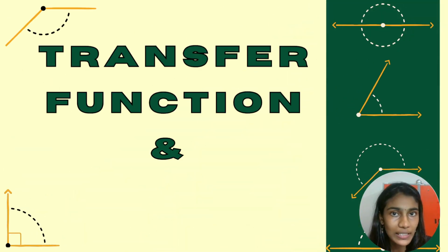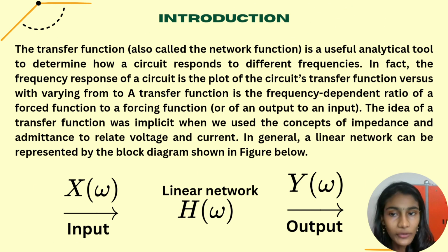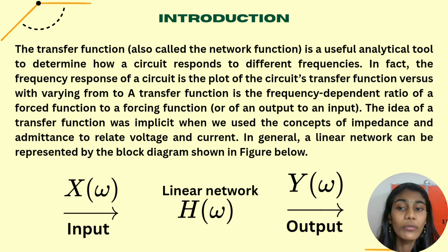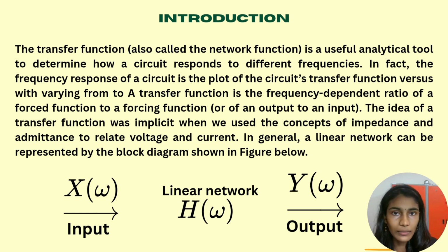Our assignment title is Transfer Function and Bode Plot. To start, let's define the transfer function. A transfer function is a mathematical expression that shows the relationship between the input and output of a linear time-invariant system in the frequency domain. It plays an important role in circuit analysis and control systems, allowing engineers to predict how a circuit will behave at different frequencies. It can be presented as the ratio of output voltage to input voltage, or output current to input current, depending on the system.